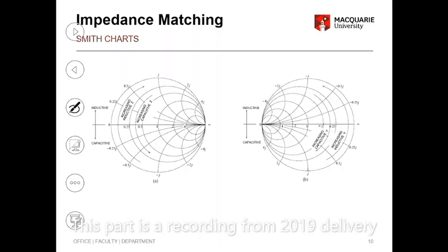So you can determine it based on this Smith chart. Now I'll go back to the impedance Smith chart here. That's the impedance Smith chart. So you always travel along a resistance circle.